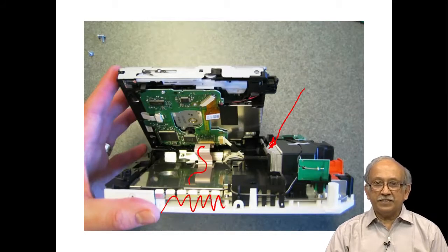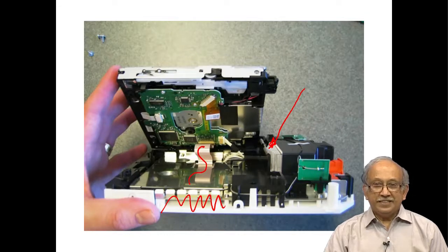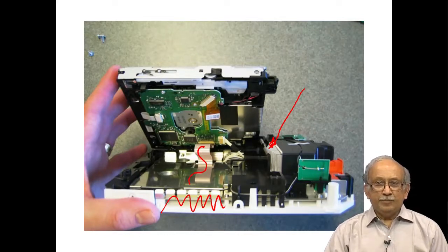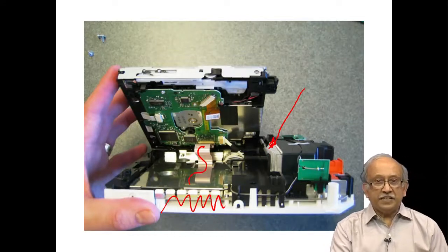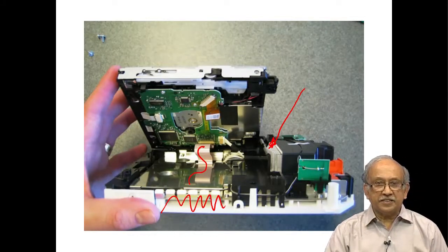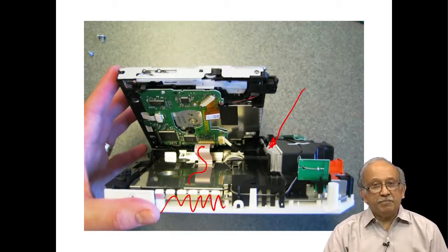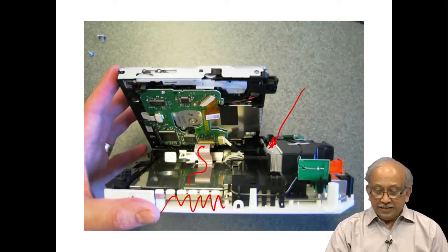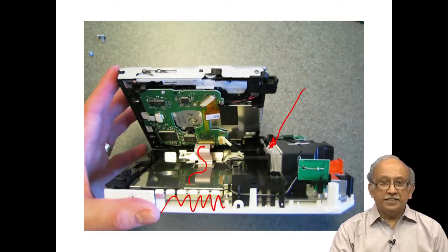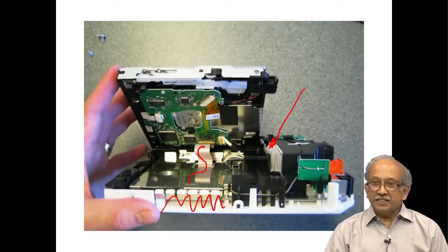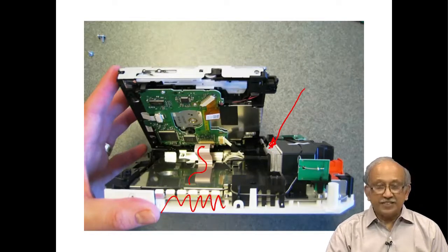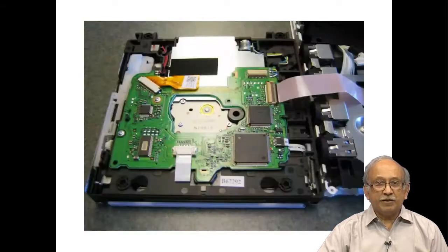Normally the ambient temperature inside an equipment is maybe 90, 80 and so on, and the devices may or may not be above that. But just next to this, imagine if you have a really hot component, let us say a resistor which goes above 110 degrees, that will be passing on heat to the black heat sink and not the other way. And most of the time with heat sinks, the mode of heat transfer is convection, and convection does not depend on color. So you will notice that a heat sink is one of the unavoidable portions of this.